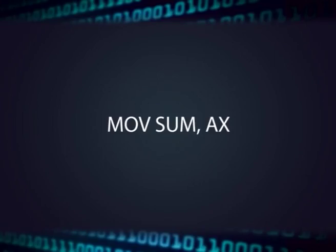In all memory reference move instructions, the effective address of the memory location is computed as the offset specified in the instruction, added with the contents of the data segment register, which is shifted left by 4 bits to make it a 20-bit address. Take an example, say the instruction is MOV SUM, AX. In this instruction, the memory location identified by the variable SUM is specified using direct addressing.